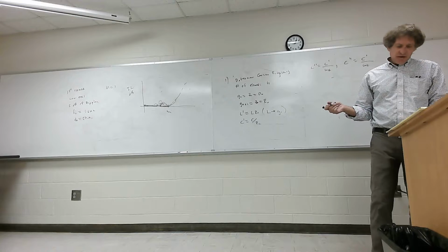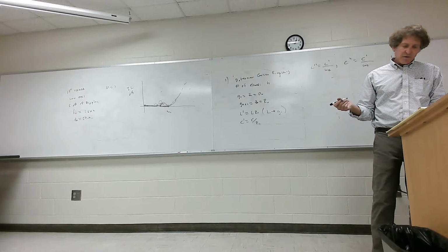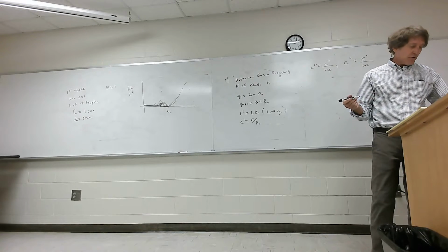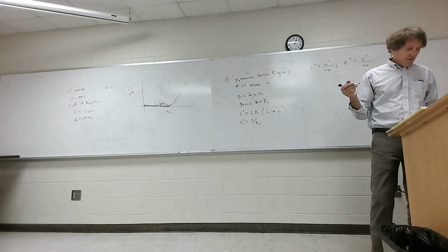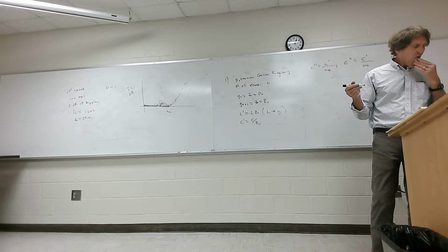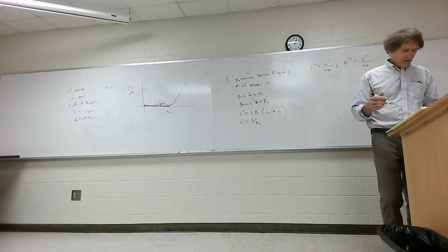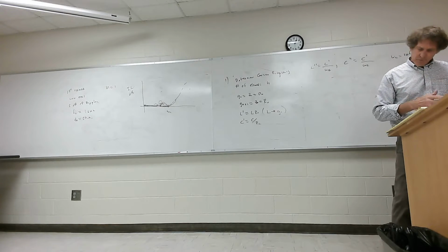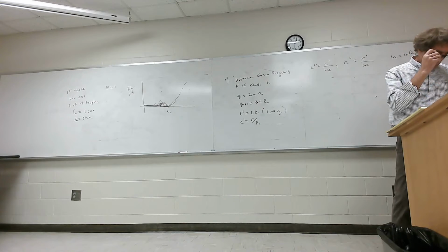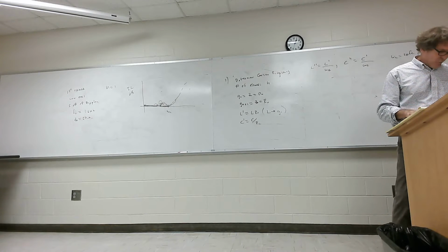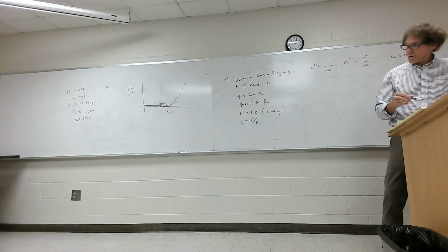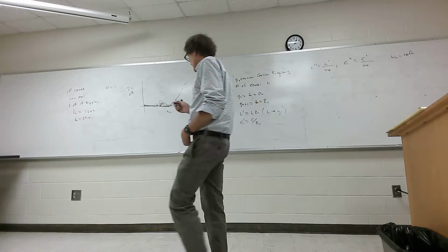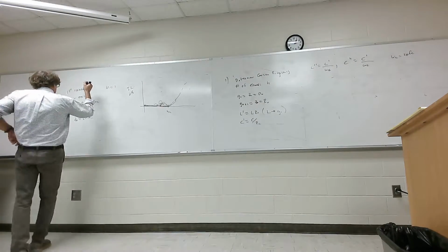So he gives these values, 3 dB of ripple, 1 gigahertz, 50 ohms, and now you have to go in that table, if you work with me on this one, if you have your books, you can see that for 3 dB of ripple, that's the bottom one. And since there's only one element, there's 2 values that you have to get. For G1, it's 1.9953, and G2 is 1. So, when you take a look at this, this filter is going to be about as easy as it gets.